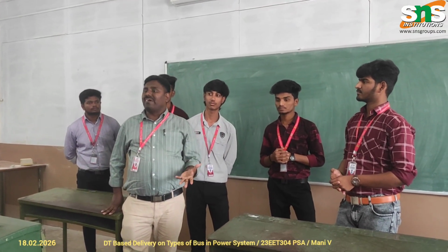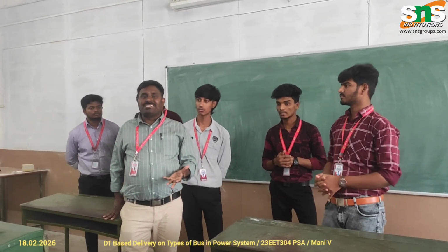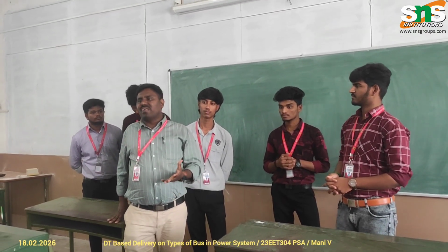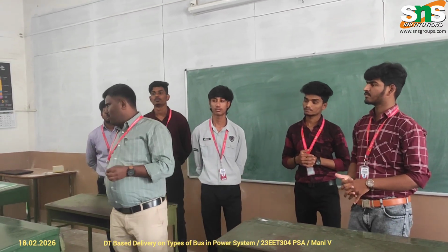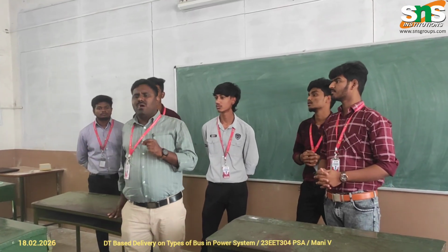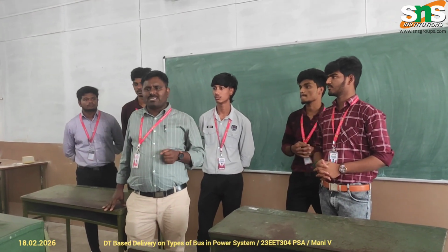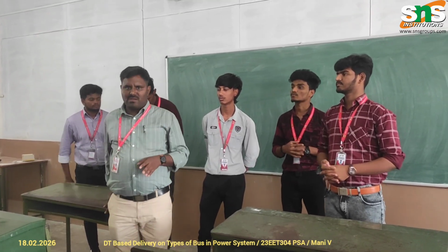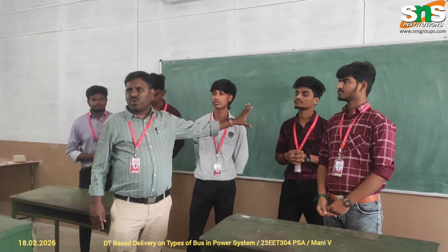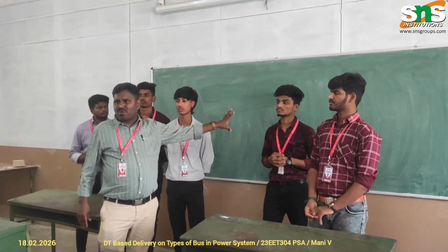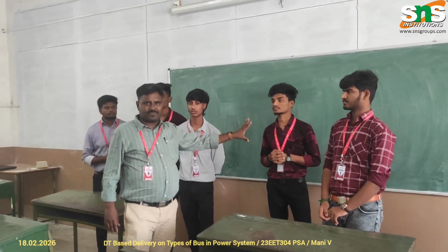So we don't know the value of the reactive power which is supplied by the generator, as well as the phase angle of voltage. So we have to determine the phase angle as well as reactive power by using either the Gauss-Seidel or Newton-Raphson method. So this is the first bus. It is called a generator bus, or it may be called a PV bus.